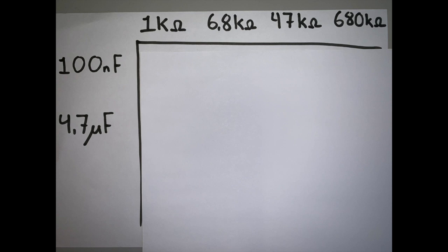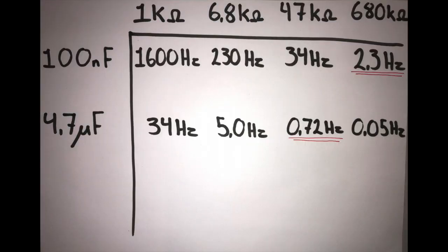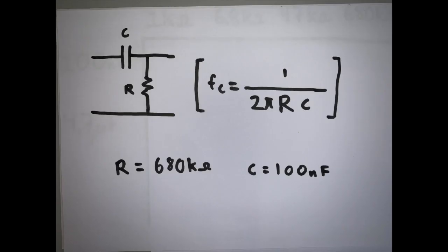2 types of filters were constructed to filter and amplify the sensor output. One passive high-pass filter and non-amplifying, and one active low-pass filter and amplifying. For the high-pass, we chose a cutoff frequency of 0.7 Hz, so frequency higher than that will pass, and use this equation to find which resistor and capacitor to use.